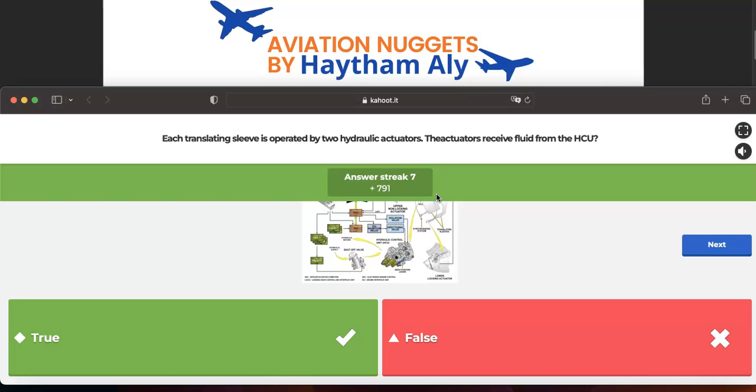The engine will go to auto idle, auto restow for the thrust reverser, and an auto thrust disconnection will happen if an inadvertent thrust reverser deploy happens in flight. Thanks to the LVDT, the EEC will know that an inadvertent deploy happened in flight, and the EEC will manage auto idle, auto thrust disconnection and auto restow.